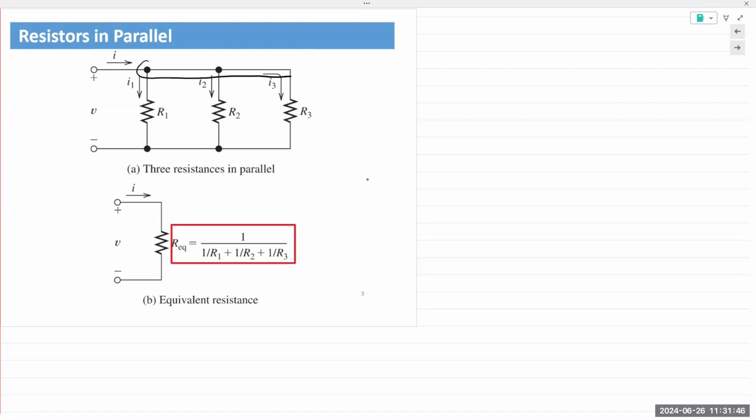And we see at the top, they're all connected together. And we see at the bottom also that they're all connected together. So electrically speaking, it's the exact same node. Even though we see multiple dots in the circuit, this is not node 1, 2, 3, 4, 5, 6. This is simply node 1, and this is simply node 2.